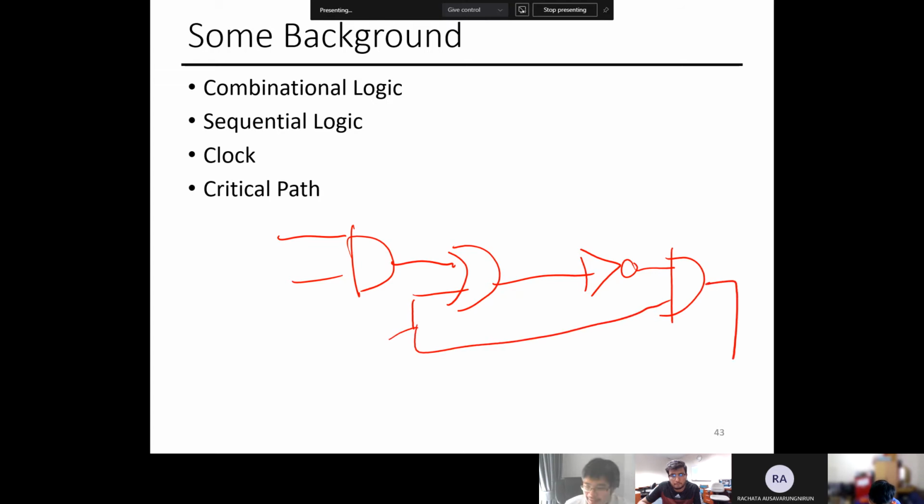If you look at this logic, which one is likely the longest road between the sources, source 1, source 2, source 3, and the destination? It's probably source 1 down to the destination, or source 2 down to the destination, which is the same length. So these are likely to be the critical path.